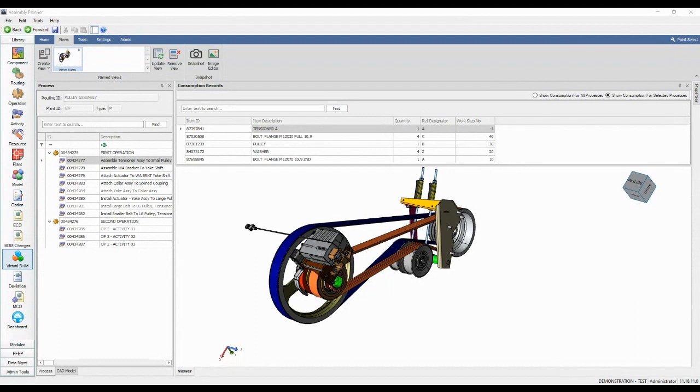So for instance, if I did not want this warning symbol here, I can simply highlight it and delete it. Same thing with the callouts, right? So maybe I don't want that image on there, and maybe I don't want that call out. And let's say I want this to point to something rather than just into nothing. So I can do all of that editing, and I can hit save image. The important point of this is there's a vast amount of increased speed and efficiency for the engineer because you don't have to redefine the whole image in case of a part revision change, for instance.